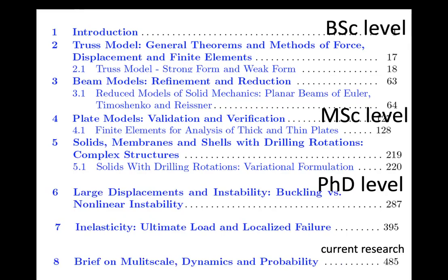So buckling would be instability with small buckling displacement. So kinematics and cos theta might be linear, but the equilibrium is nonlinear. That's how Euler obtained his π² EI divided by L². And then nonlinear stability, you have like a large pre-buckling displacement. So you have a kind of different situation that's certainly more difficult to solve such a problem.